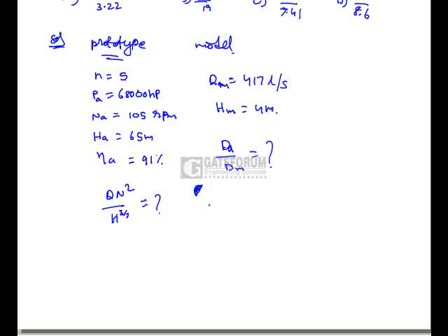So here the flow rate in each turbine comes from the power formula, that is efficiency into WQH, where W is the specific weight of the fluid, Q is the flow rate, H is the head available, and efficiency represents efficiency. So here PA is equal to 68,000 HP. First convert it into watts and then substitute all the values. From this we can get QA, that is equal to 87,385 liters per second. So this is the first step.